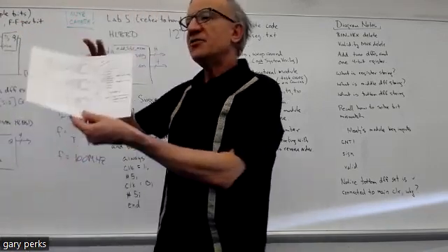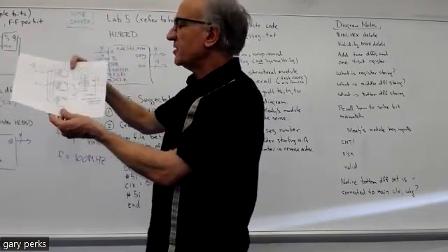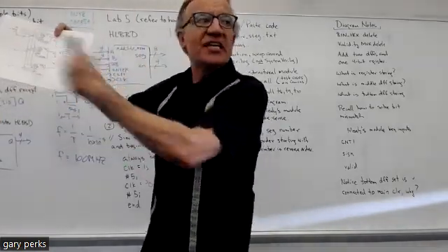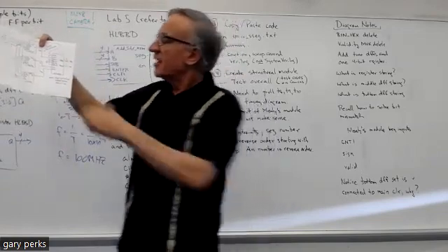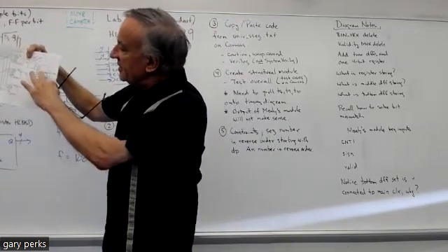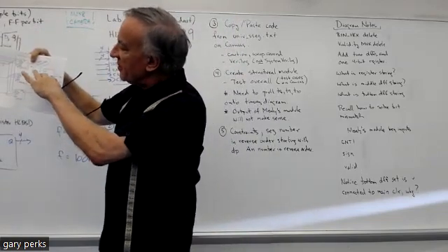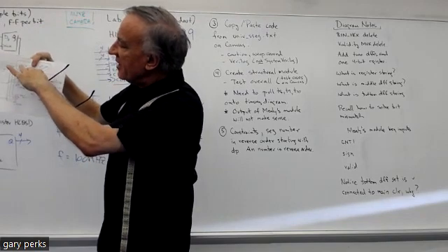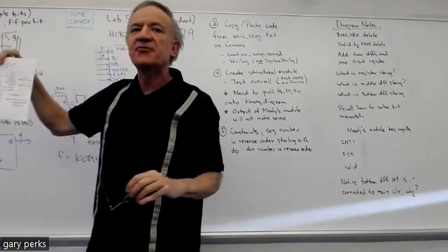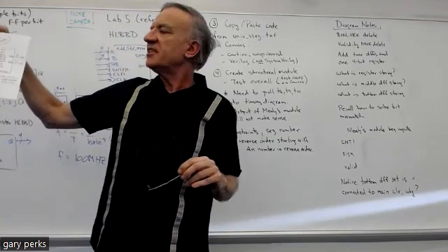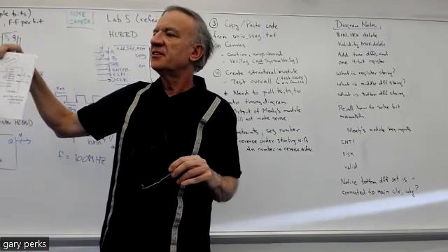So to verify that your overall design works, you have to look at what's going into Mealy's module. There's input CNT1; look where that input connects. It connects to the Q output of that 4-bit register. What is that register storing?